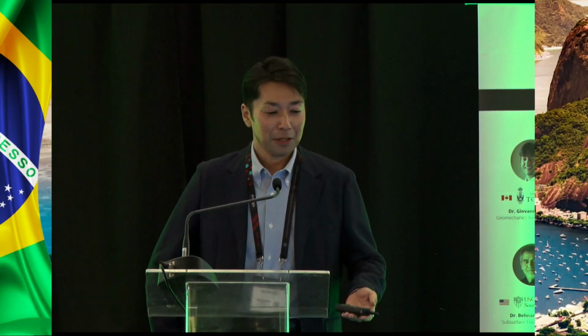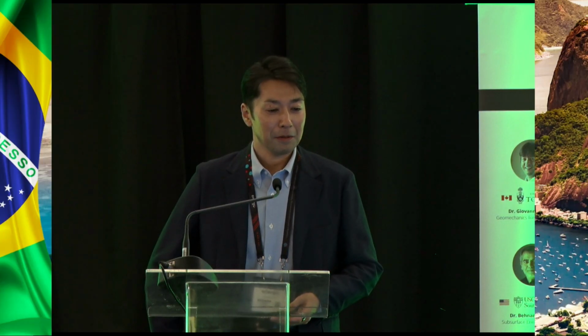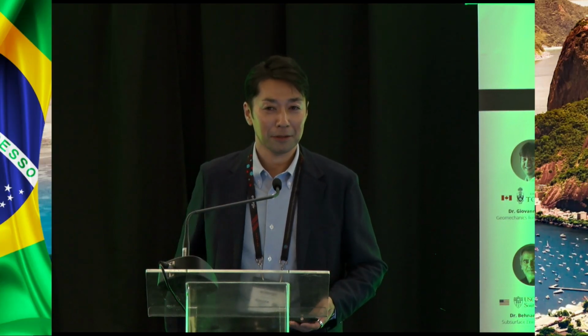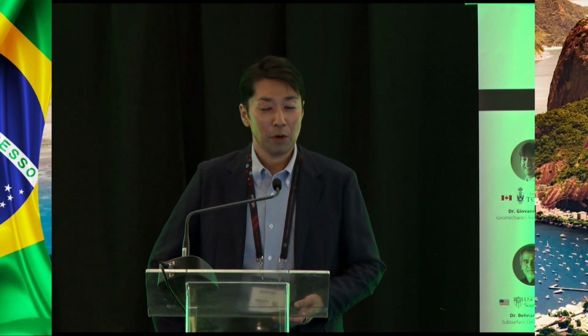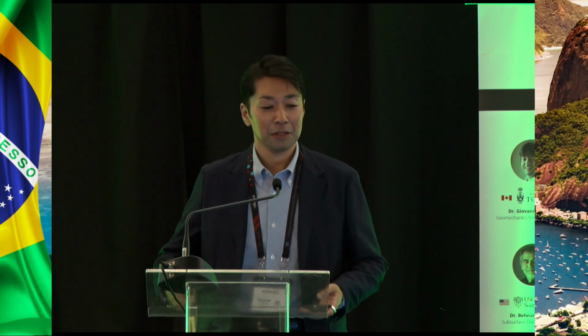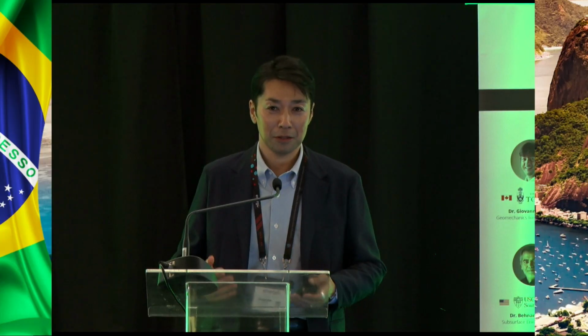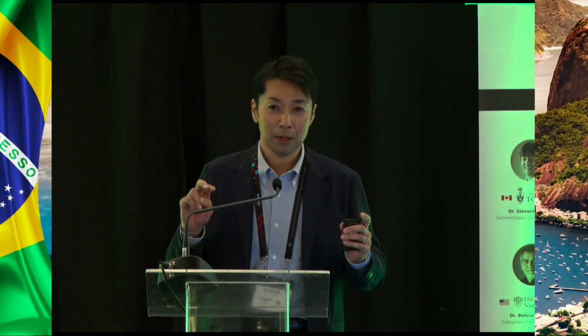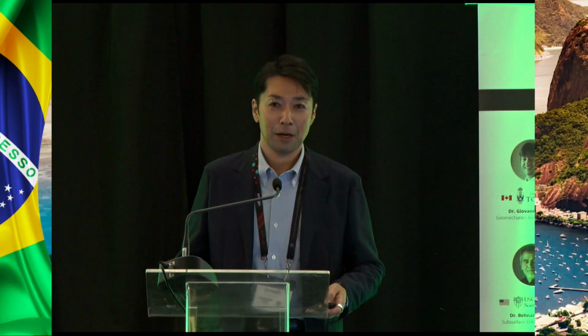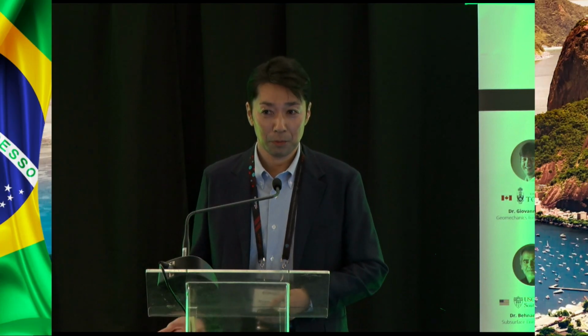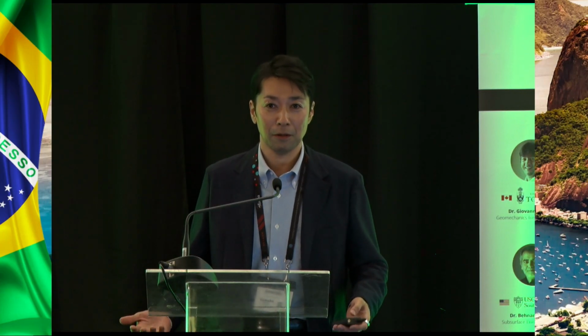And in this particular EOR method, it's called EOR here, but rather it can be viewed as a well treatment where we change wettability of rock near the wellbore. So we hopefully change the relative permeability in favor of oil production for the long term.